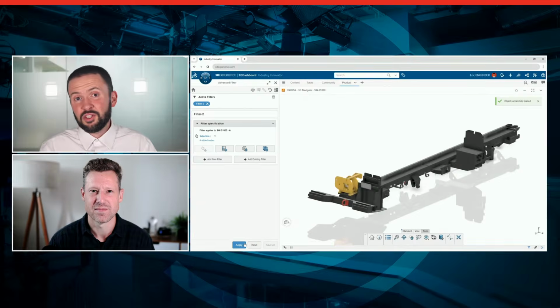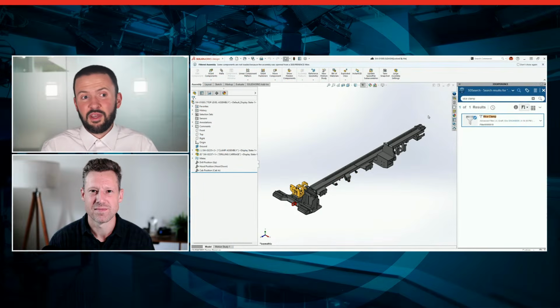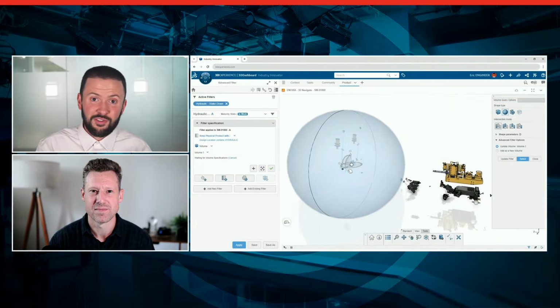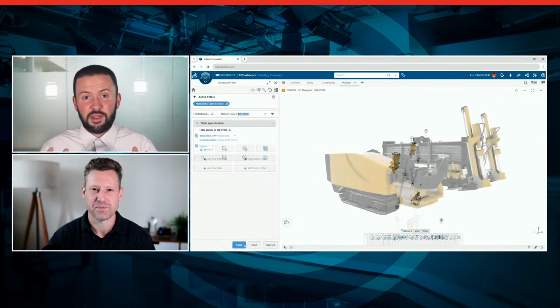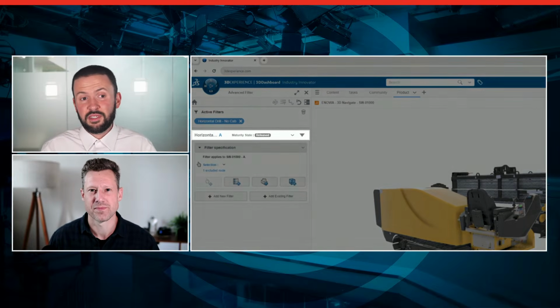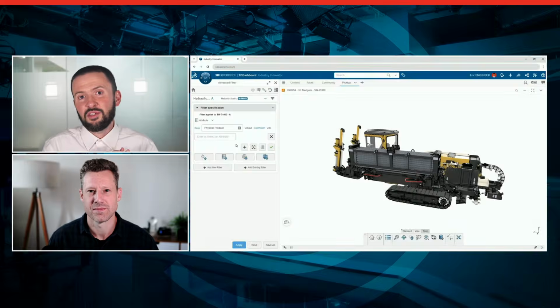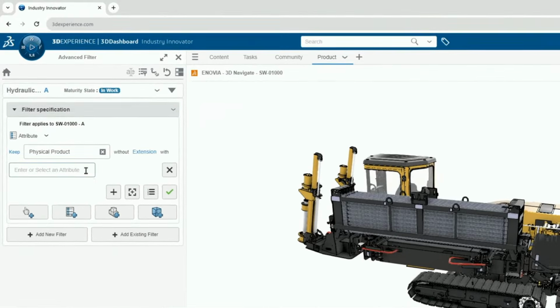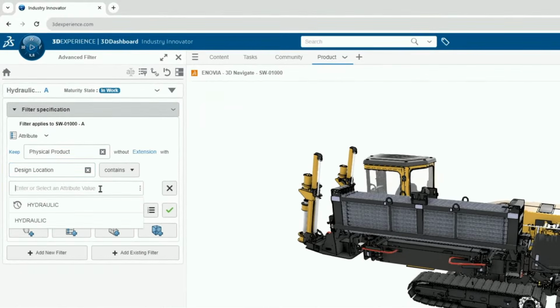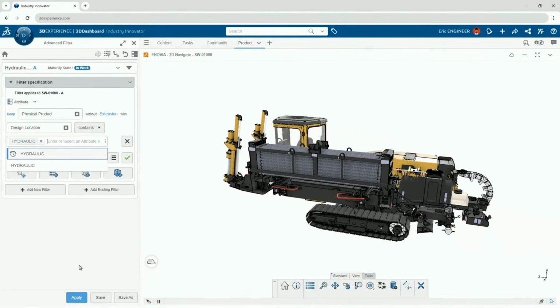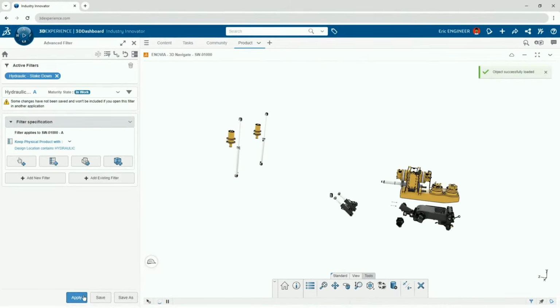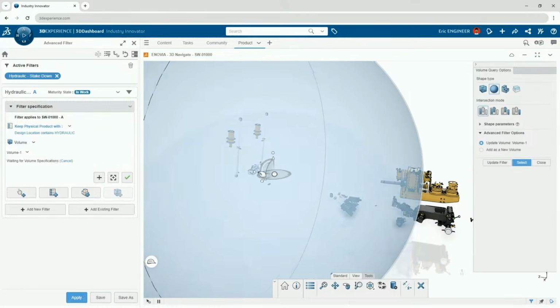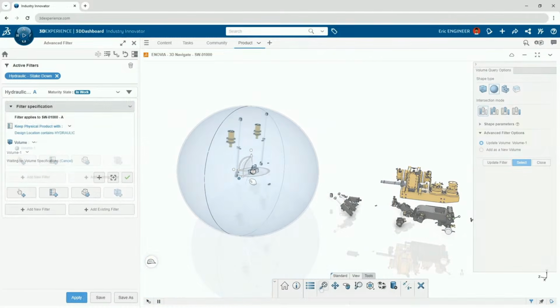And we didn't show this earlier, but you can insert them as referenced drawing views. So in terms of limiting overhead with your larger assemblies, this is a great option to investigate. And this came out in 2025 FD03. So even if you're not making that full jump to 2026 within the next 6 or 12 months, you can still access this functionality.